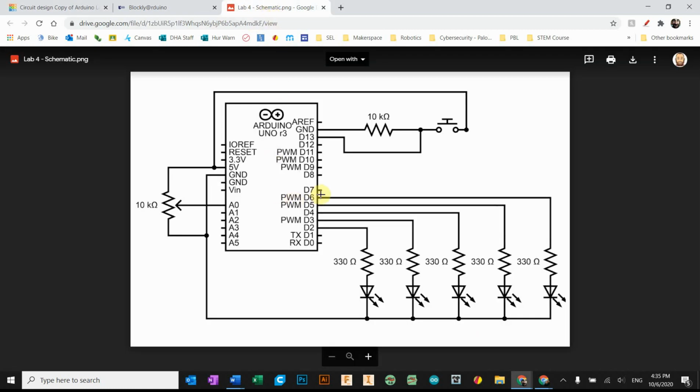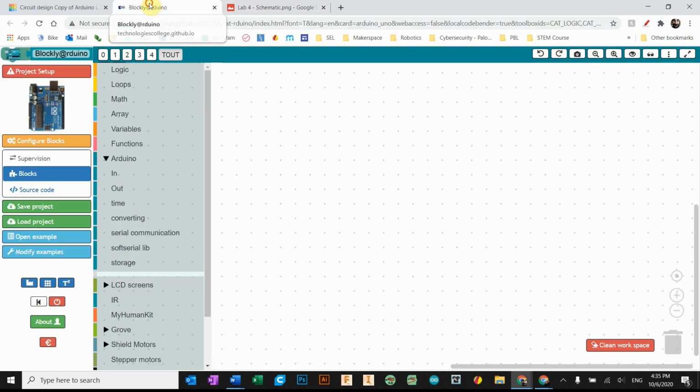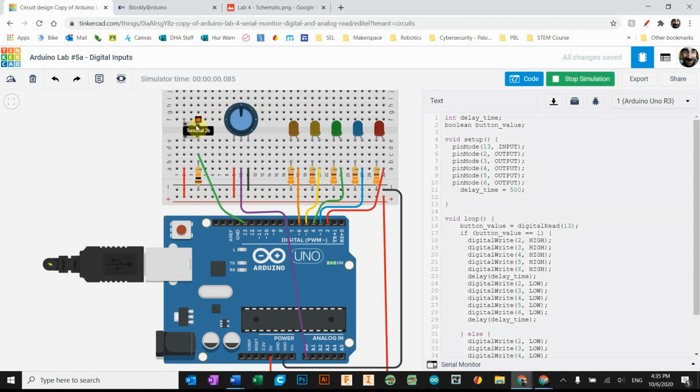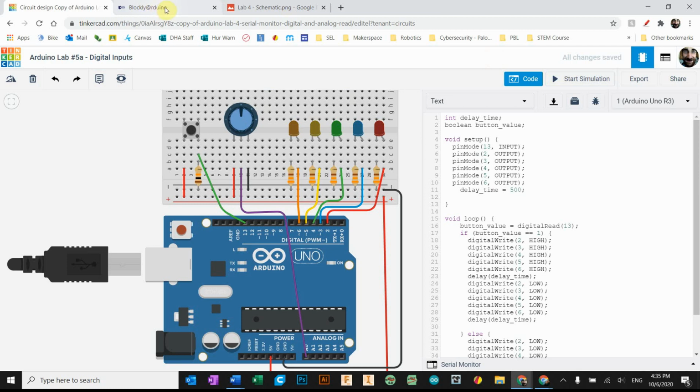So if you want a schematic, I have that right here. That looks amazing. Love it. One thing you'll notice here, this button, when it's pressed, we have a signal going in. When the button's pressed, the signal goes across and then follows this green wire all the way down to pin 13. We have this 10K resistor. This is something called a pull-down resistor that just eats up any leftover charge so we don't fry our board. First, let's take a look at what this circuit does. When I press play to simulate and press this button and hold, the lights blink. That's amazing. Stop.